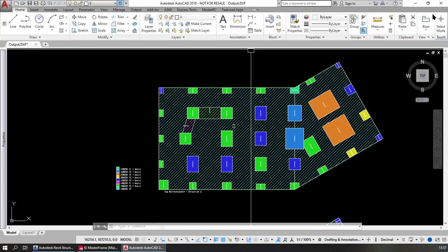Somebody asked about piled slabs. Piled slabs are done in the same way. The only difference is that you can't do the punching shear unless you have a column underneath. So I would always recommend that the column is placed underneath each pile location.